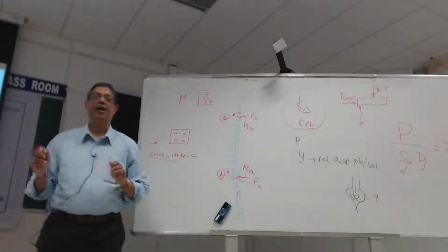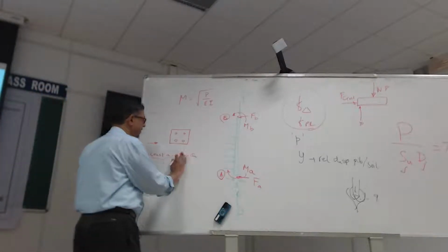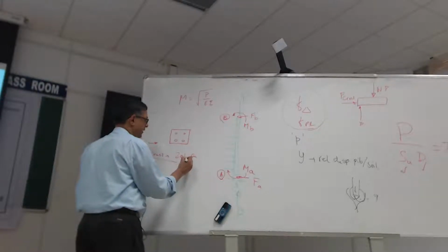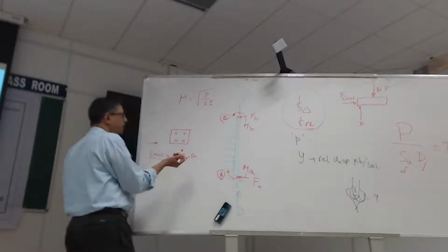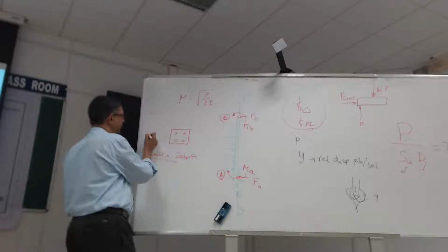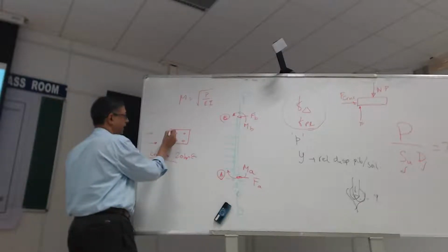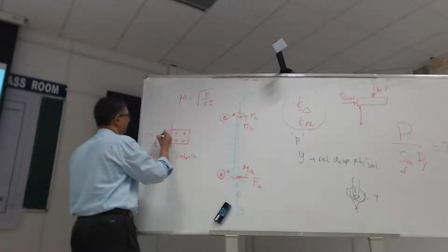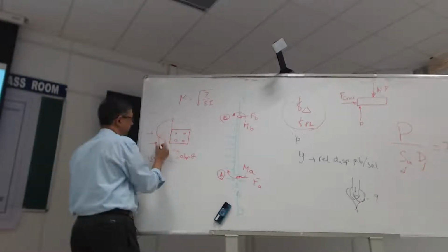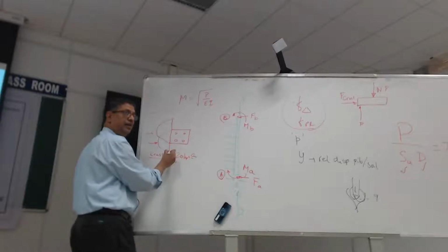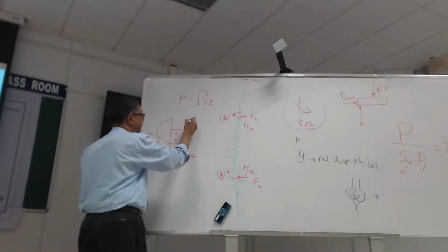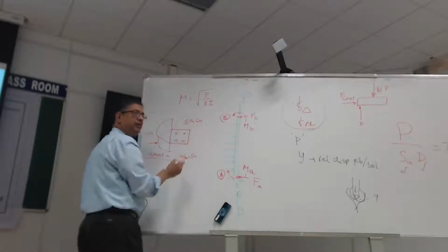Right? However, you say this is 20 kPa, then you can very well imagine the soil is trying to flow that way. I'll get my bearing capacity failure. So this should, from upper bound, I know the answer to this is 5.14 cu.